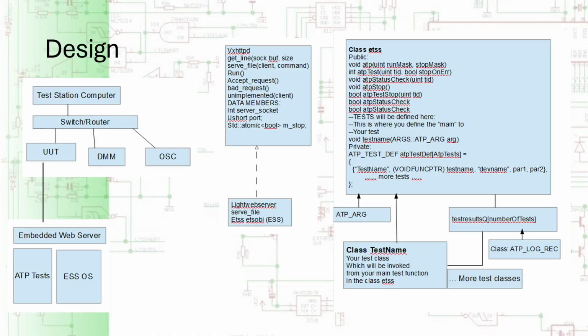I can go into more details why they're used the way they are, but that would involve going into the history of GPIB and how that type of parallel port communication works. But nowadays, most of these devices all have an Ethernet port, and you simply talk to them just like you would with any other computer via sockets. And you can write a simple client socket program to do SCPI commands.